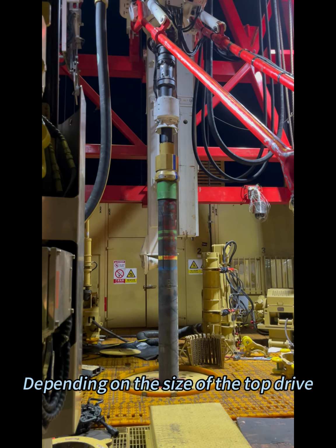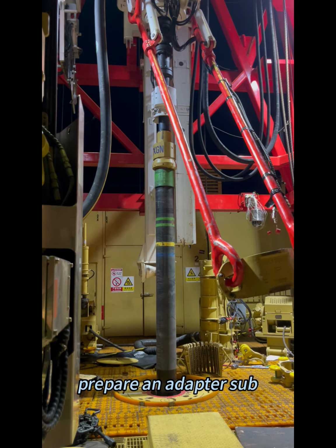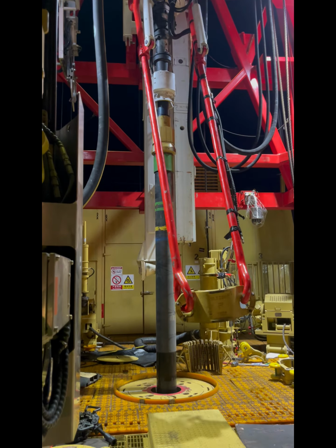Depending on the size of the top drive center pipe thread connection, prepare an adapter sub. Additionally, select suitable extended lifting links or extension links as needed. The total length of the lifting links is related to the equipment length, adapter sub length, and top drive model. If the wellhead is misaligned or when running threaded casings, for example, thumb threads, consider using a box thread protector to better meet field requirements.